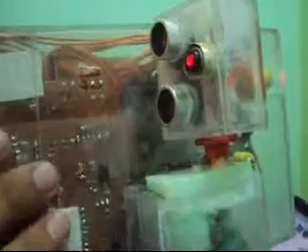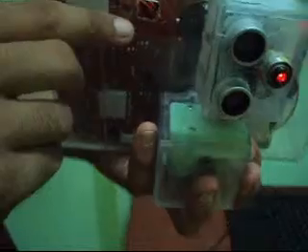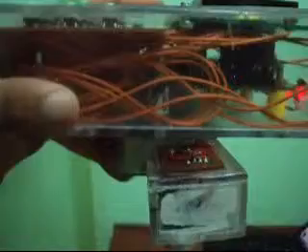The servo platform is attached to a small brushed DC motor that is connected in the PID closed loop with the help of the second accelerometer at the top of the device. The accelerometer is MMA8451Q from the FREESCALE semiconductor. The purpose of mounting the ultrasonic distance sensor on the servo platform is to keep it always parallel to the ground so that it will measure the perpendicular height of the device above the ground.